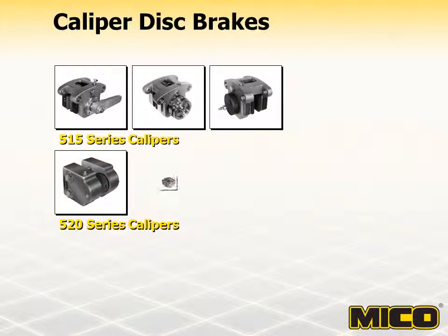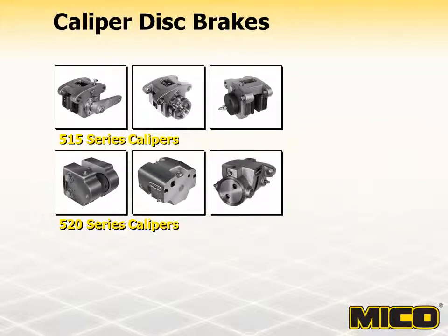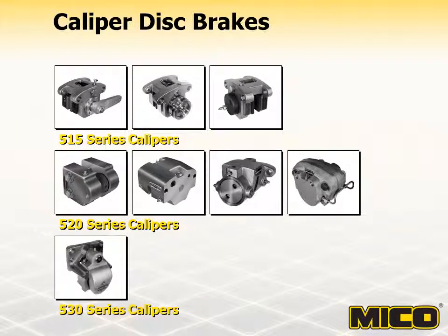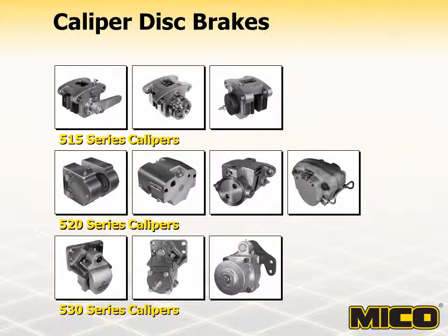The 520 series brakes are available with different types of housings depending on the application. 520 series brakes are physically larger than the 515 series. Of all the MICO Caliper disc brakes, the 520 series is the most commonly used in dynamic braking. All 530 series brakes shown are spring apply hydraulic release. The main difference between 530 series brakes is the output torque provided by the spring pack. These brakes are normally used for parking or static braking applications.